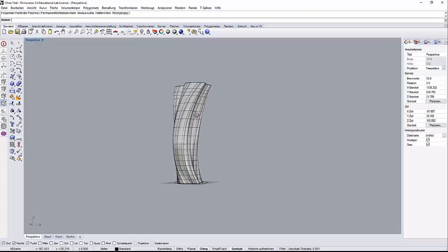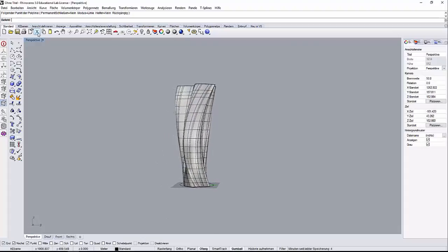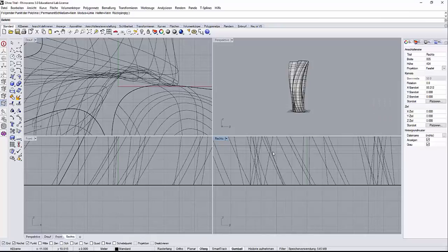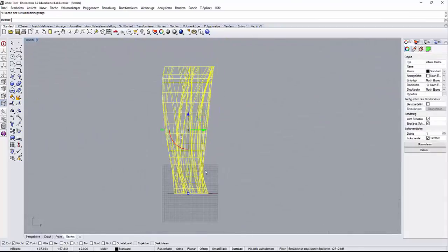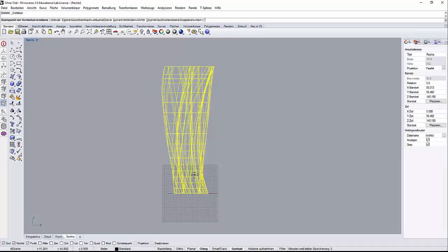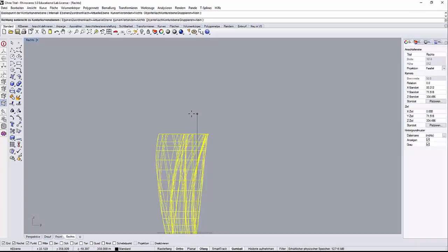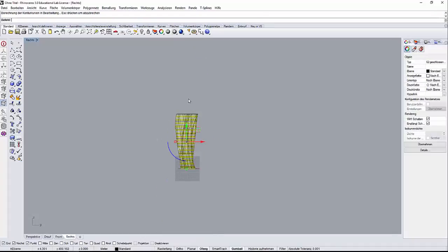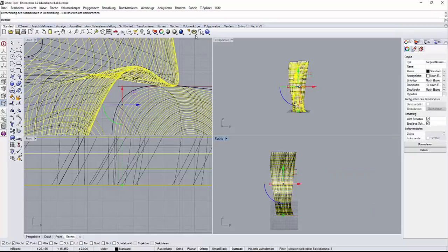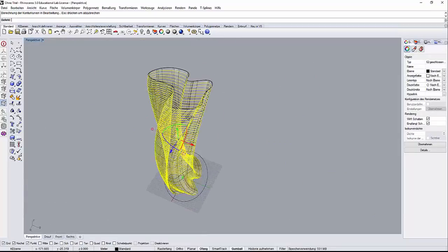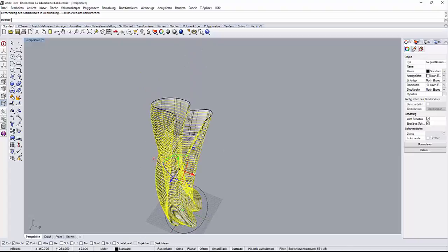Now let's start adding some floors. How do we do this? Very quickly, I select this element, and since I'm considering this being some sort of hotel or something, let's do a contour. These are all tools that I explained to you last semester. The contour will go in this direction. The distance will be, say, 5 meters. And now we're going to have all these floors drawn like this.